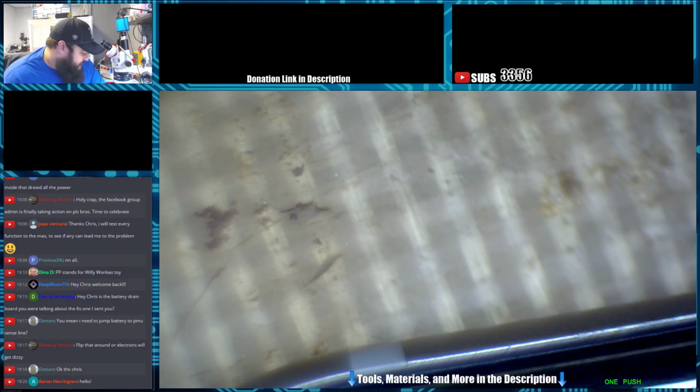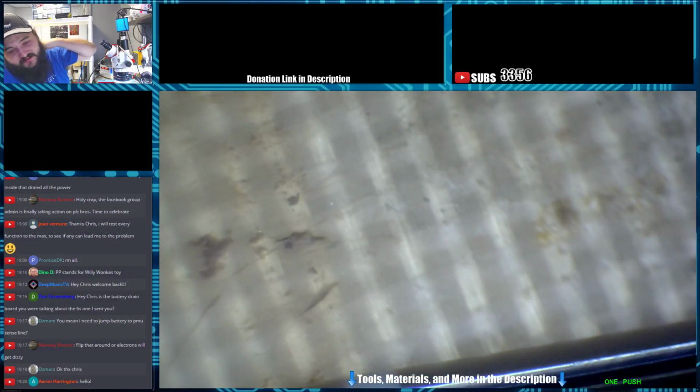No problem, Osmond. See if that works. Pop a dead battery in it and see if it'll charge it while it's off. If you've replaced Tristar and you know Tristar's good, that's the only other thing I can think of. Maybe your dock flex too. Make sure your dock flex is good. Also make sure your dead battery is okay. If the battery is bad, it will not charge if it's dead because it'll throw some weird errors for the phone.